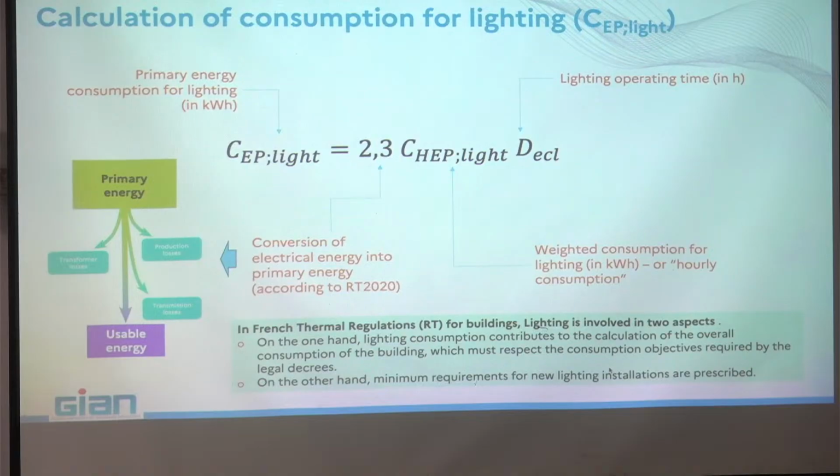The French law for building construction includes what we call the thermal regulation principles, which are written in the law. And the law says if this value here is above a fixed figure, that can be, for example, more than 5 kilowatt hours per year and per square meter for offices, then your license to build the building can be denied.